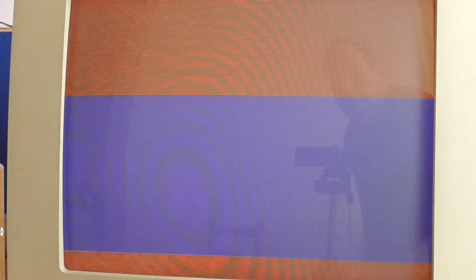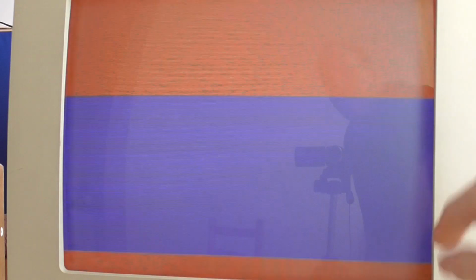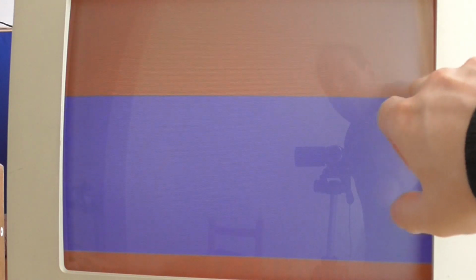The first thing to do was to replace some of those no-ops with instructions for changing the background color. So here I changed from blue to red shortly after the vertical flyback period starts. So this is actually inside the bottom border, and then I change it back to blue again at some other raster during the main part of the display. Now I don't know how well it'll show up on camera, but there's actually some flickering going backwards and forwards on this very last raster, and that's because I haven't quite got the pattern exactly right here. It is possible to do that and you can get this completely stable.